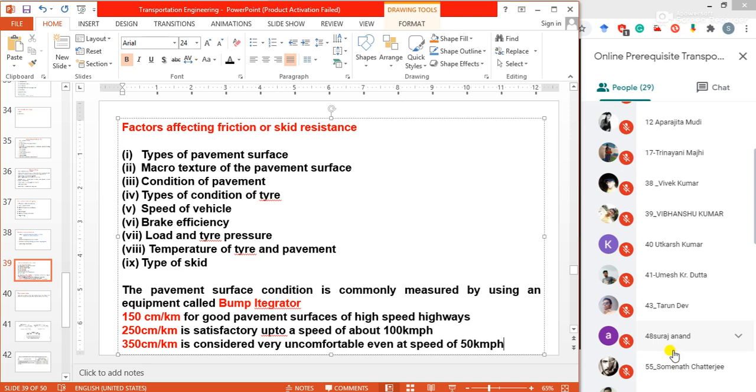This is due to moisture. If our drainage is okay, if we make such a road where the water cannot be blocked or stand for much more time, then the durability of the road will increase.